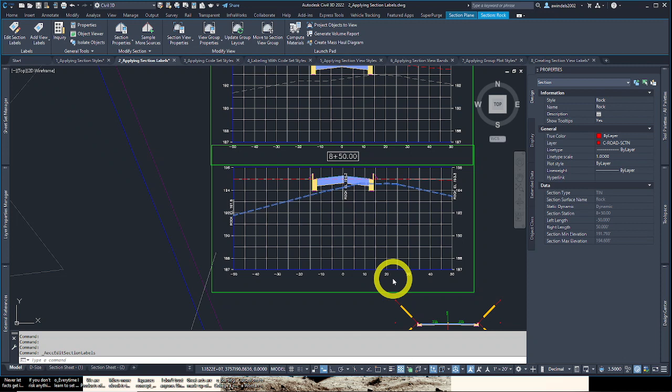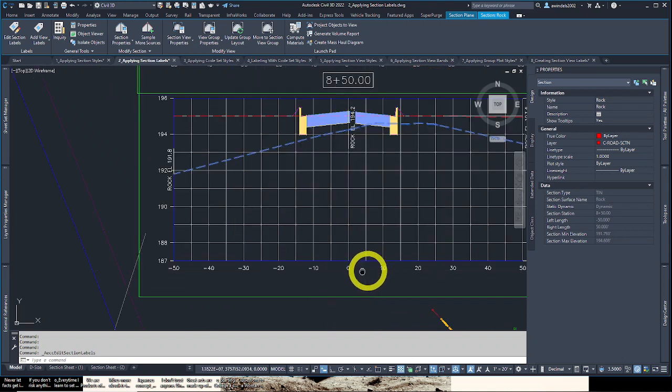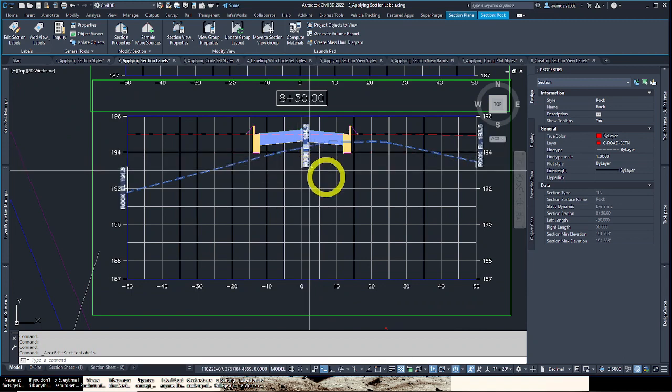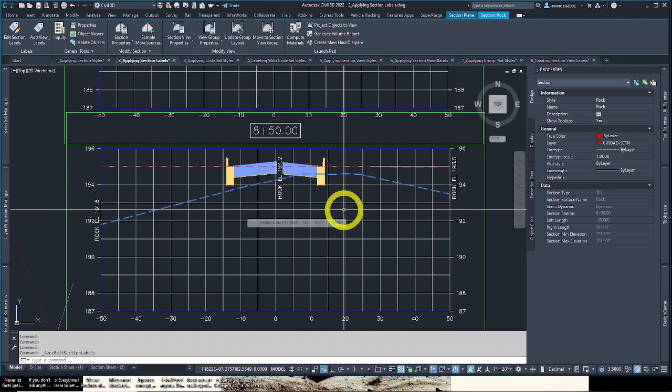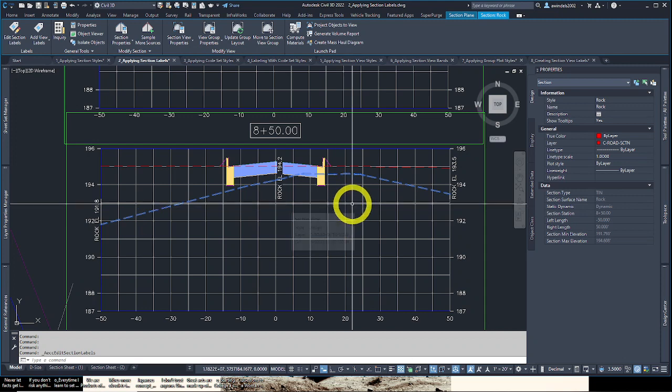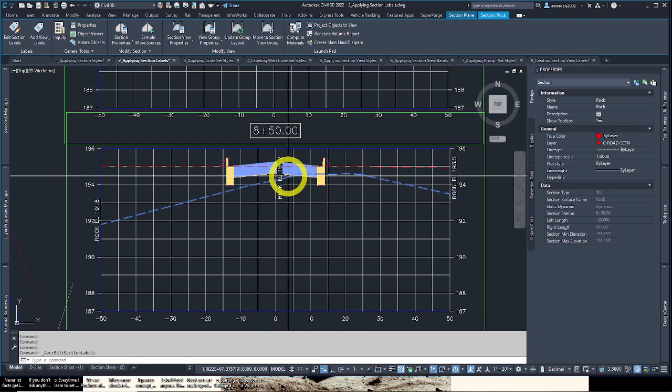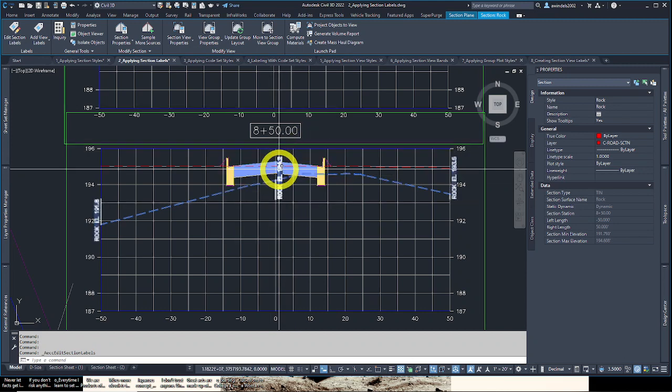For example, in the previous steps we just did, you specified that the labels should be aligned at the bottom, which they are here. So these labels come in with a certain alignment with respect to the bottom. There's a lot more to it than that, but we messed with, it was called the dim anchor opt setting. We could have messed with the dim anchor val setting. It is the offset from the anchor point. So it says how far off this point we have an offset, which enables you to fine tune the position of this label, for example, and even more.